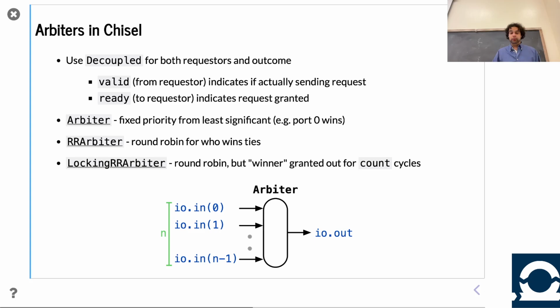Yes, exactly. So every single one of these ports has their own ready and valid. This is one of the things where you can see with Chisel, you're starting to appreciate some of the advantages. There's nothing groundbreaking here. We have all these ports. These ports can be declared with Vec of n ports. We've seen that. Each of these ports can be marked Decoupled, and you get the ready and valid too. So you can see very quickly, not very many lines of code is generating a lot of wires, and these wires aren't wasteful. You would need those to run this by hand in Verilog. You still need that functionality.